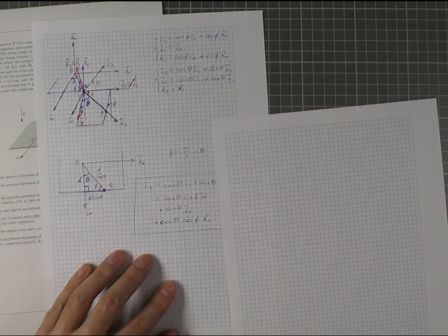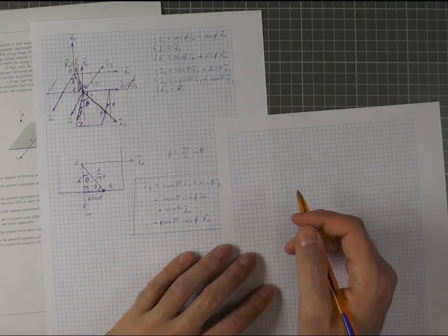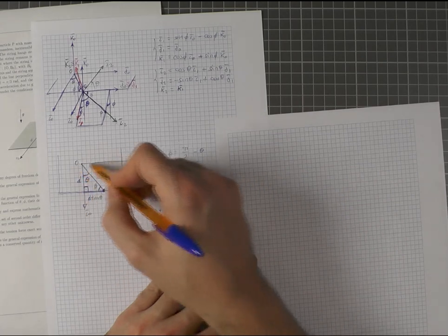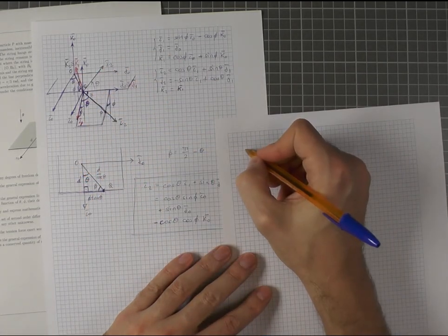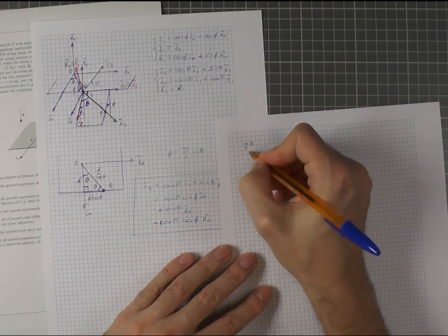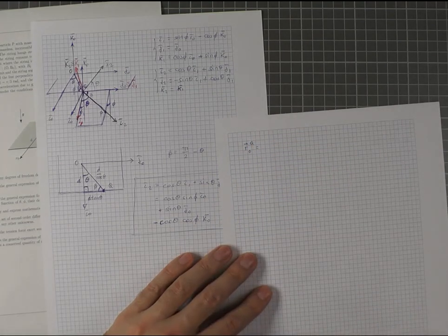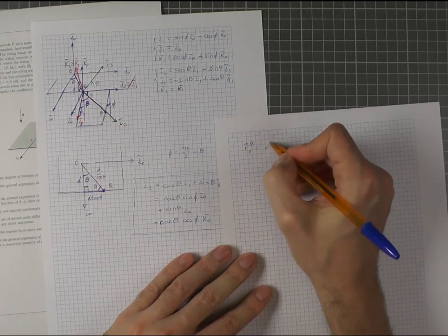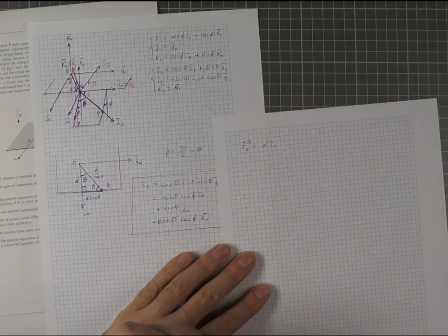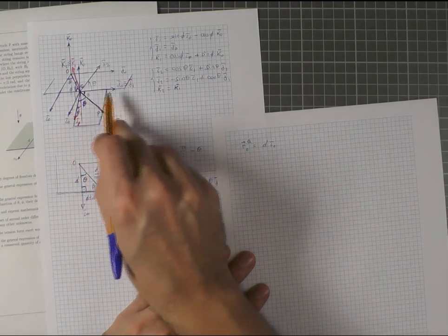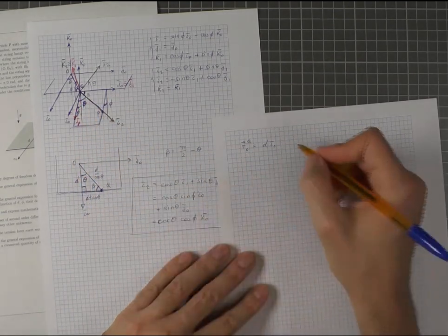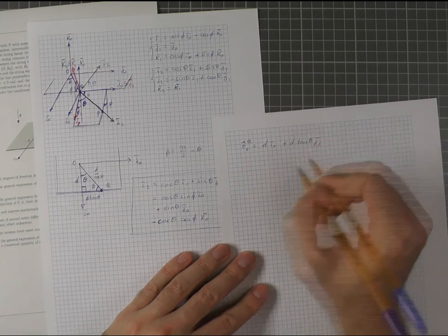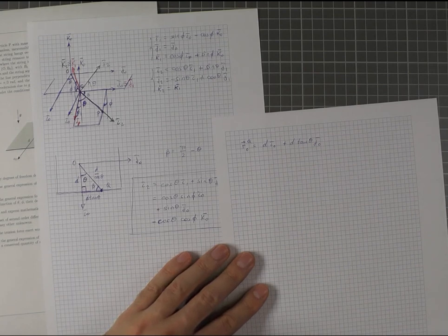Once we have that, and using all the vectors that we have, finding out the position of point Q as seen from reference frame 0, from the origin, is relatively straightforward. That position is given by moving from O to the edge of the table, a distance d, that gives us d times I0, and then moving to the right along J0, a distance d tangent theta. So there you go, that gives us the position of point Q.